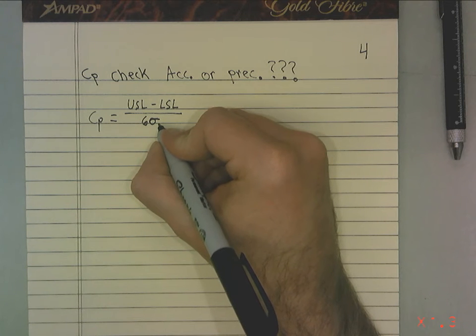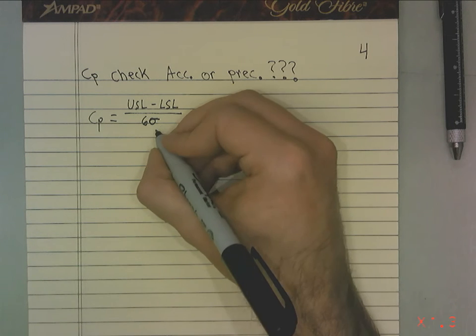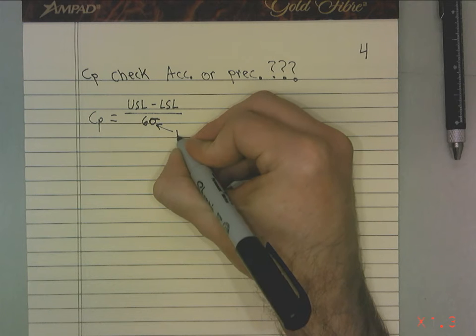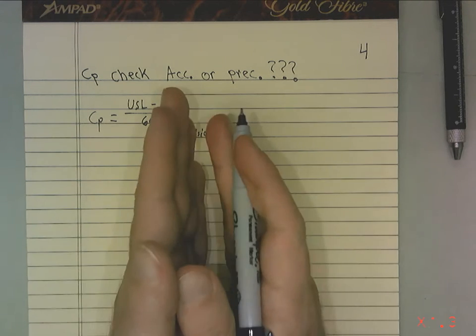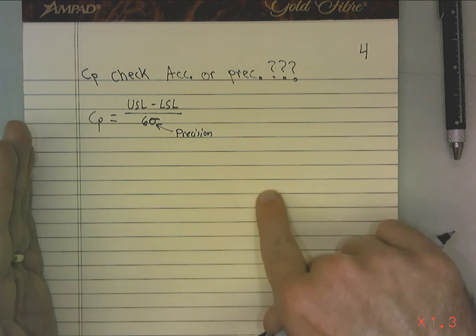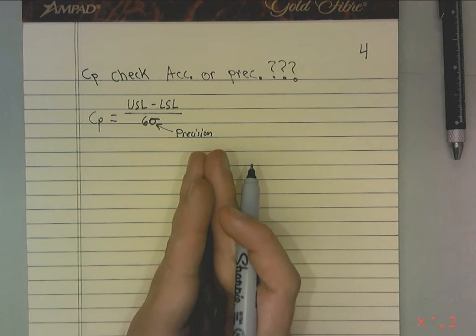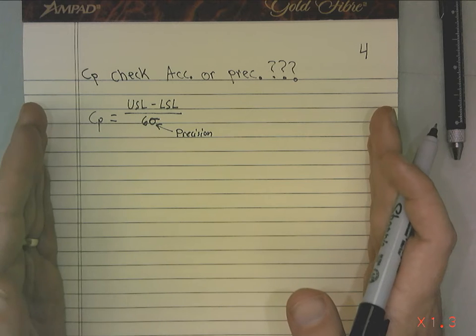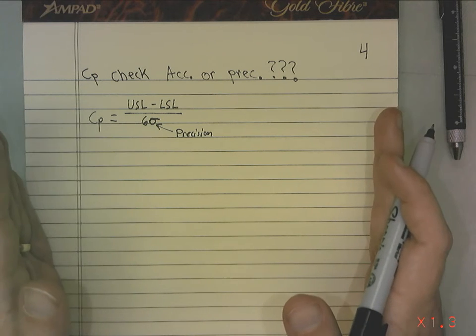Standard deviation, is it associated with accuracy or precision? Check the accuracy and precision review, but this is precision. Standard deviation is associated with precision, because we can have a huge spread on a normal distribution, like a big flat curve. On average, we're making good parts, right? We've doubled the part size and we've halved the part size. They're all bad parts. But on average, if we just average them together, it's great.